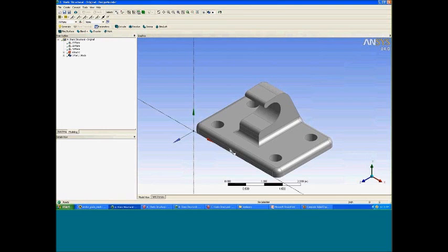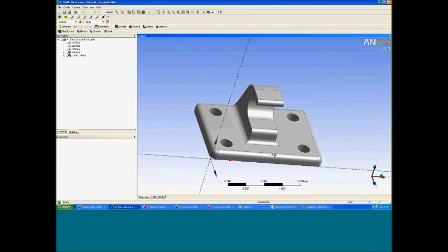Now, what I'd like to preface this with is that creating a brick mesh and doing this slicing and dicing technique is very much a personal approach to how you would decompose geometry. So if I gave this part to 5 different people, I could almost guarantee that I'd get 5 different geometry subdivisions and 5 different meshes in the end. So there's no right way, but what I'll try to do today is show you how I would go about doing this, and hopefully give you some clues into the process that I go through.